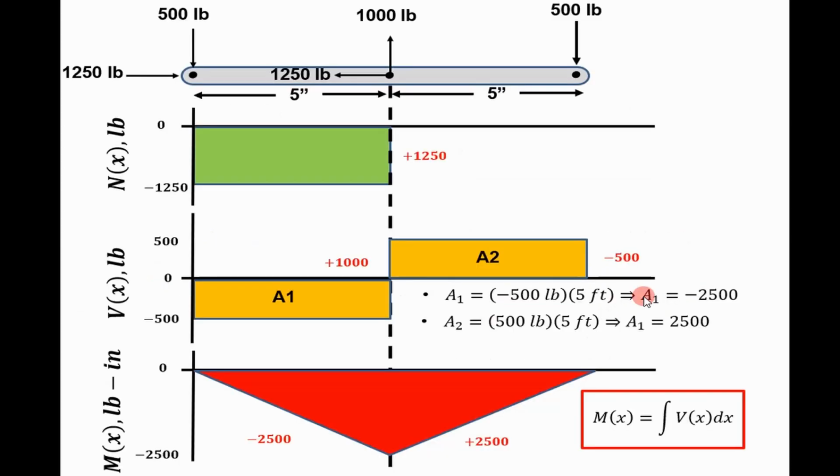Okay, so a lot's going on here, but basically here's your member with all the external forces in their X and Y components. So now when we think about normal forces, we've got to look at the X direction forces. So this one would be something we consider in our normal force diagram, and this one too.